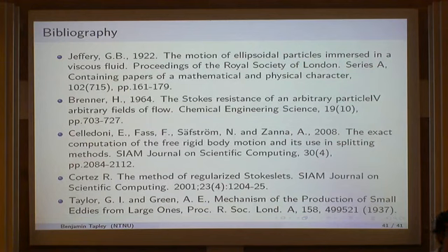The fluid flow isn't coupled to the particles at all. The particles are just being carried along by the flow. Yeah, so it's what we call one-way coupling, right? The particles are affected by the fluid, but the fluid evolves independently of the particles as if they weren't there. Because I know people in the Met Office who do this for a living. It's very important to the dispersal of pollutants, or volcanic ash, or other things coming from power stations that blow up. That was the famous first example. Big fires, where's the smoke going?